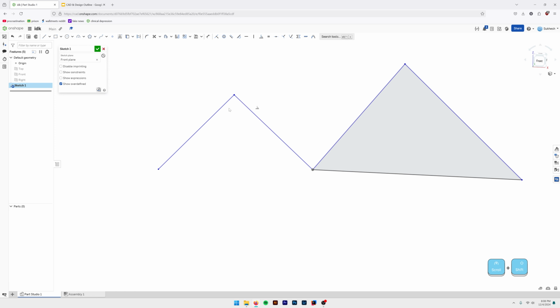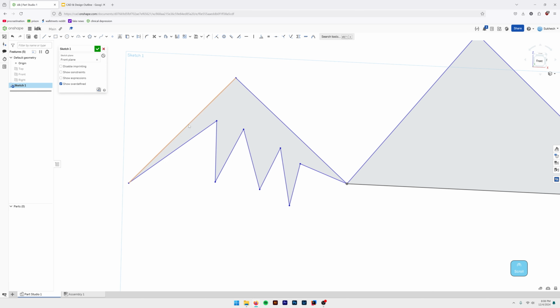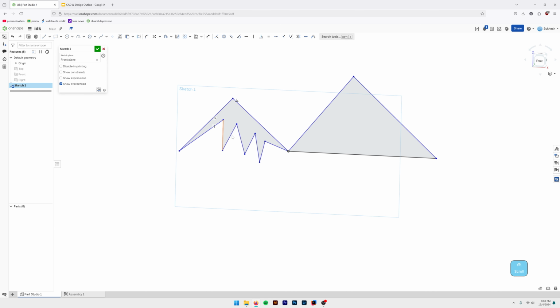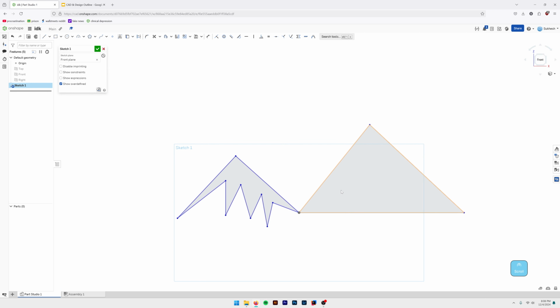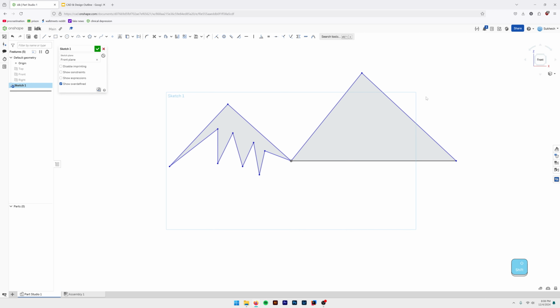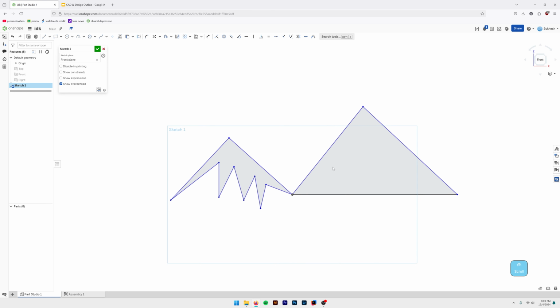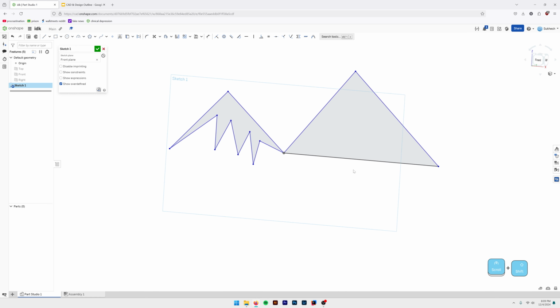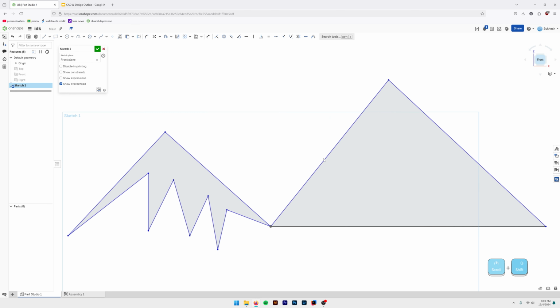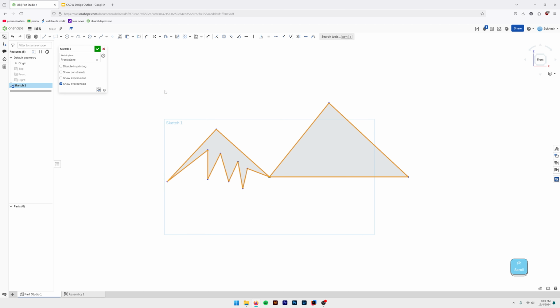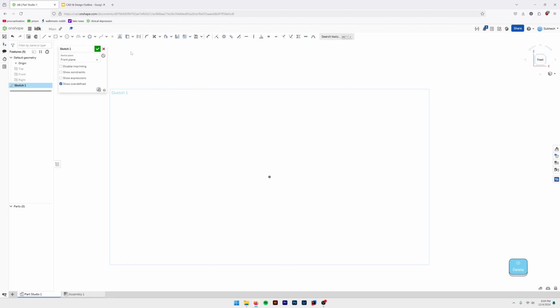Onshape has no clue what to do here because we didn't complete the shape. So if you just complete it, I don't know, make it like a zigzag or something, but whatever. Once you complete it, Onshape will know, okay, this shaded gray thing is something that I can extrude. Important concept to remember. You can also navigate through these cubes if you want. I just prefer to do my scrolling way. Remember that my controls are different from yours, but you can just consult your settings to see what your panning and rotating controls are.